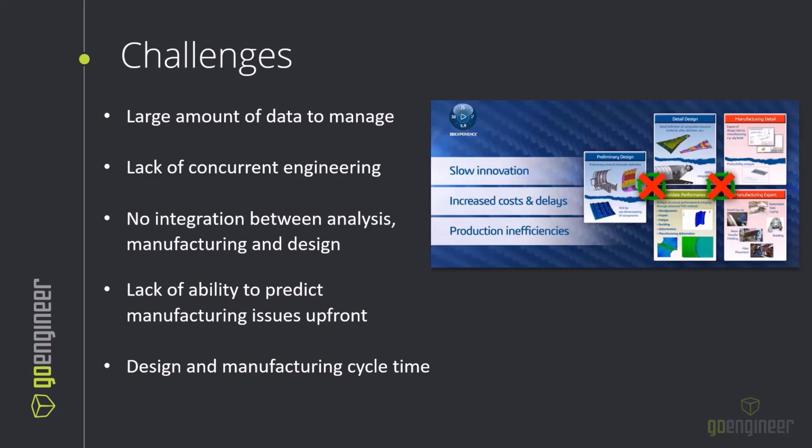For example, when you bring in data and load it in, CATIA will only load it in piecewise based off of the data that you need or want to see. Everything else is kind of just shelled representations, and the full definition is not brought in until you activate or probe that data. Talking about 3DEXPERIENCE specifically, the first time you open your data, it's pulled from the database, and at the same time, it's building a cache file of that data. So upon subsequent openings, it's instead pulling from that cache instead of from the database, as well as when you selectively load in your data. This way, your data loads in a lot faster.